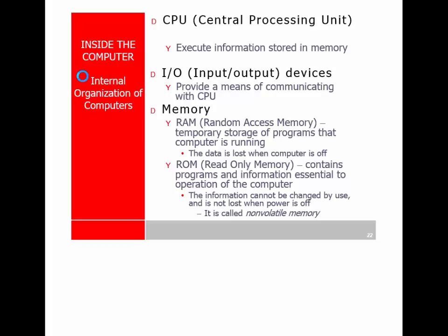When we look at how memory is configured, ROM and RAM are configured to the microprocessor exactly the same way. The only difference is in normal operation, we can't write the ROM. So ROM is a correct term. Random access is not a correct term. They're both random access. But this is memory that we can read to and write to. So read-write memory is a much better term for that.